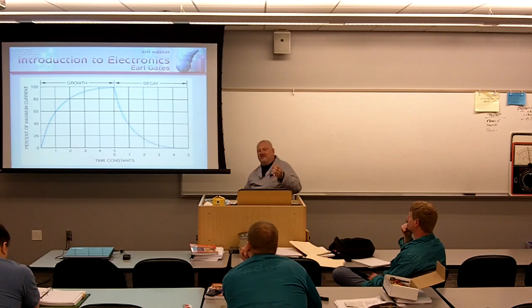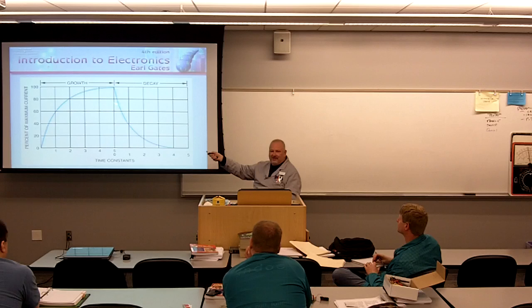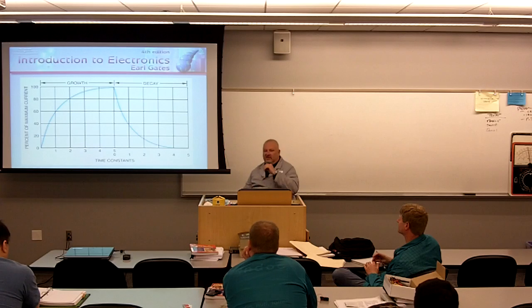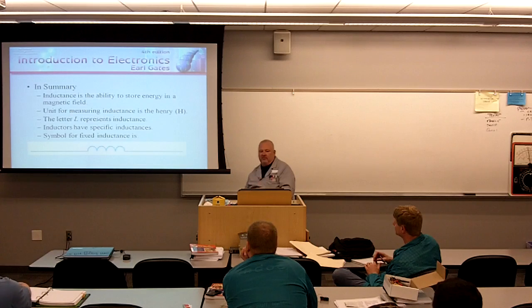Then as soon as you shut that circuit off, current's going to try to go from 100% to 0, but because that magnetic field is collapsing, I don't want to decrease, I want to keep it 100%, but I can't, oh crap, all the way down to 0. But because that field is collapsing, it's going to try to prevent that change. That's why we use these. Can inductors affect voltage? Absolutely. If we're affecting current, definitely will have an effect on voltage.